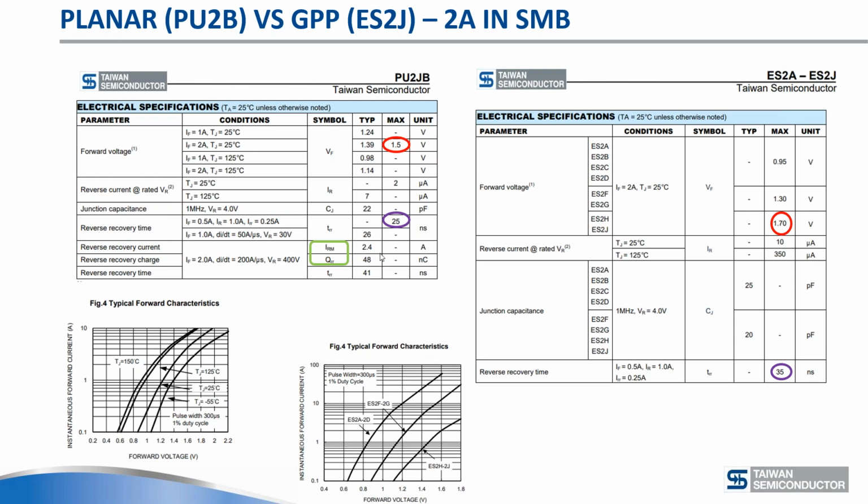Then, of course, you get a much higher QRR and reverse recovery current, because they are determined by the dI/dt. And of course, the TRR also varies quite a bit with this application. So these are applications which are closer to what the customer actually uses it for.